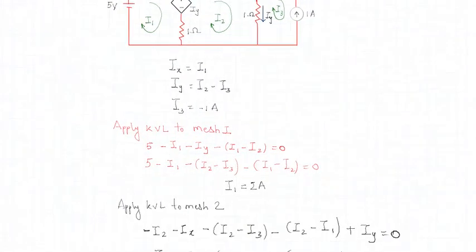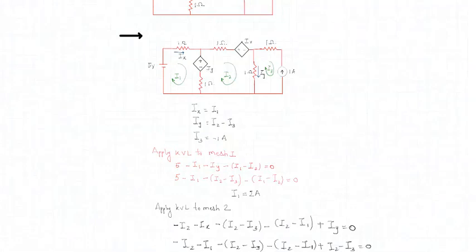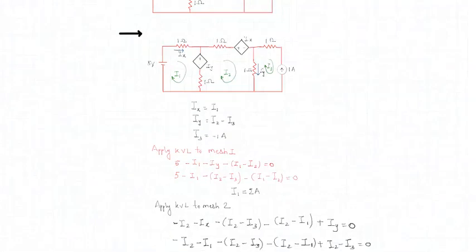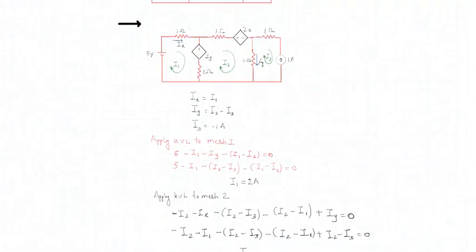So if I just verify it here, what is the equation we have obtained? Let us start. Minus I2 means I am talking about the current through the 1 ohm resistor is minus I2. The next is the voltage source, so it is minus Ix. When I come to this 1 ohm resistor, what is the current here? It is I2 minus I3, so minus of I2 minus I3.